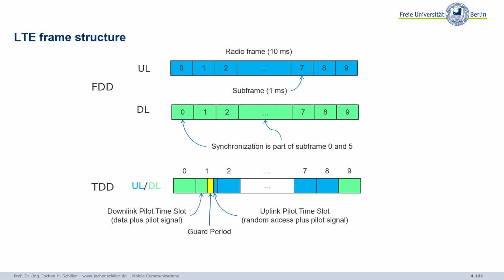necessary, radio frames of 10 milliseconds, so no more CDMA as I said, but now back again with certain slots, but the user data is distributed in a different way. So we do not have a time slot per user. So not at all. That's handled in a different way. As you see here, we have a radio frame of 10 milliseconds, subframe 1 millisecond. I will come back to this subframe on the next slide.